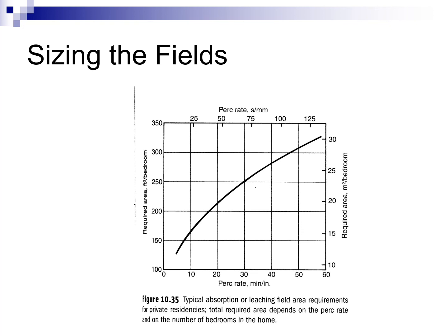So this does not count the number of bathrooms or the square footage of a house, but the number of bedrooms. This comes about because in Westchester County and most of the more rural areas, the way the population is estimated in a house is based on basically the number of bedrooms plus 1, which is generally what we design for population-wise. So if it's a 3-bedroom house, we're going to assume that there are 4 people living there.